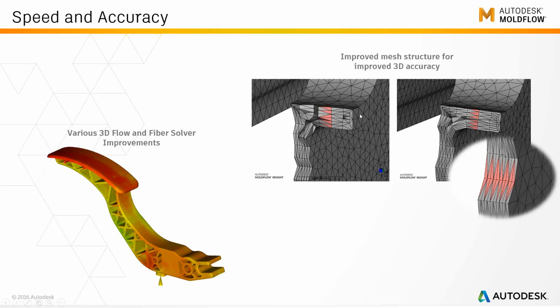But one of the outcomes of those benchmarks, or the focused development teams, is that we made some rational decisions on bumping up the number of elements through the thickness from 6 to 10 by default. This is something that I think most customers already did anyway, and we've been making hints over the years that it would be a good idea. But we had not actually formalized it in the default behavior.